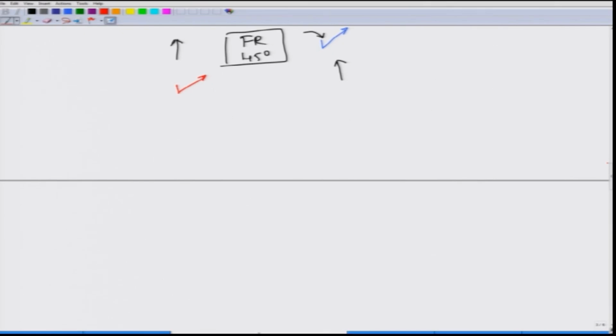Okay. What does an isolator look like? Initially we are talking about what is called a polarization dependent isolator. For a polarization dependent isolator, we assume that there is a vertical polarizer at the input. So, if I come in with horizontal and vertical polarization, only the vertically polarized light will come out.